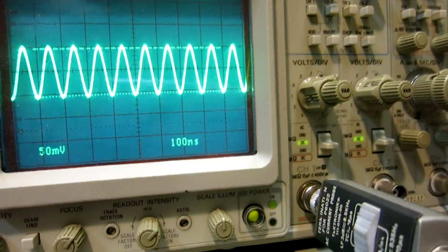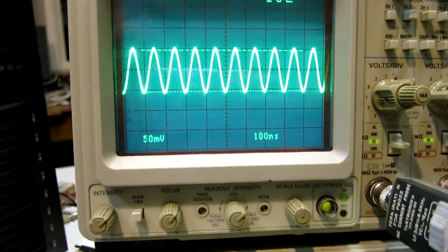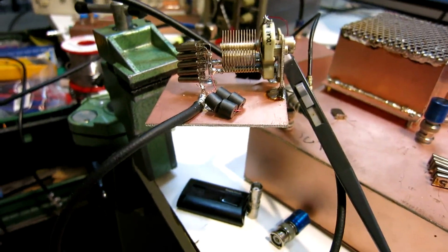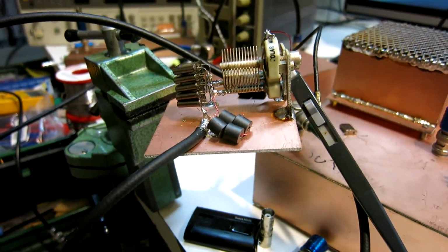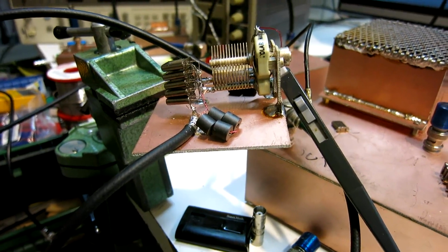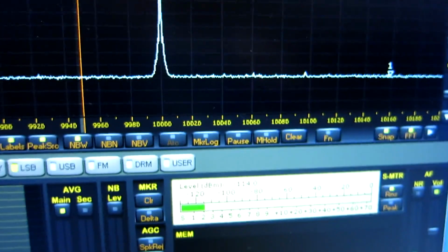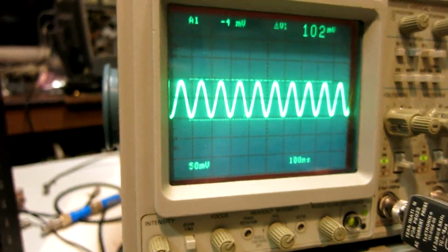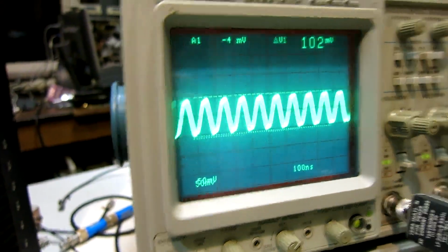That is 35 milliamps RMS, or about 4 milliwatts distributed over 5 crystals. So less than 0 dBm per crystal. Problematic. Now I'm testing just one of those crystals, and the problem has disappeared, and the current is very close to the same, but just through a single crystal.